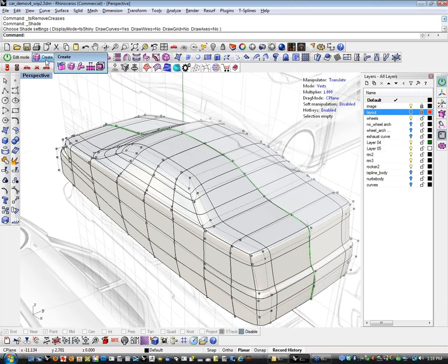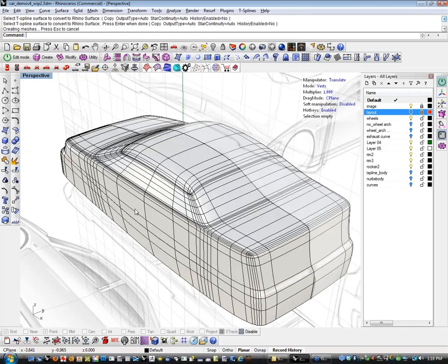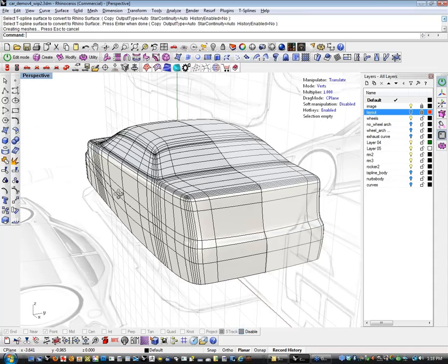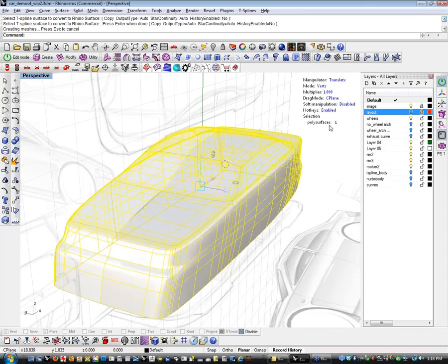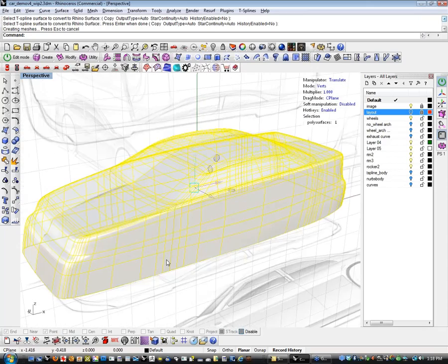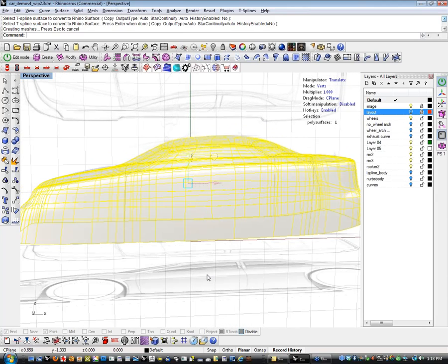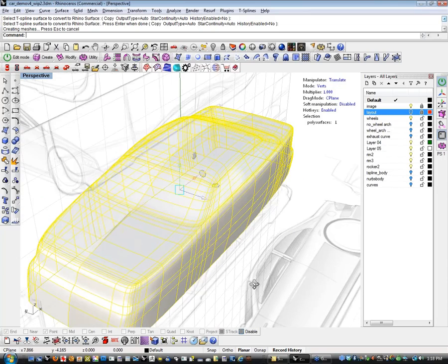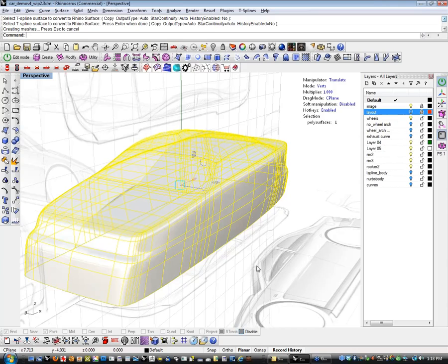It's a long, drawn-out process: you right-click on this button here, and you click on the model, and it's NURBS. All right. This is now a NURBS polysurface. You can trim this. You can boolean it, and cap it. You can do whatever you want to do. It is a NURBS surface Rhino model that you've always known and loved. Single button click. Now, the downside is you can't go back.